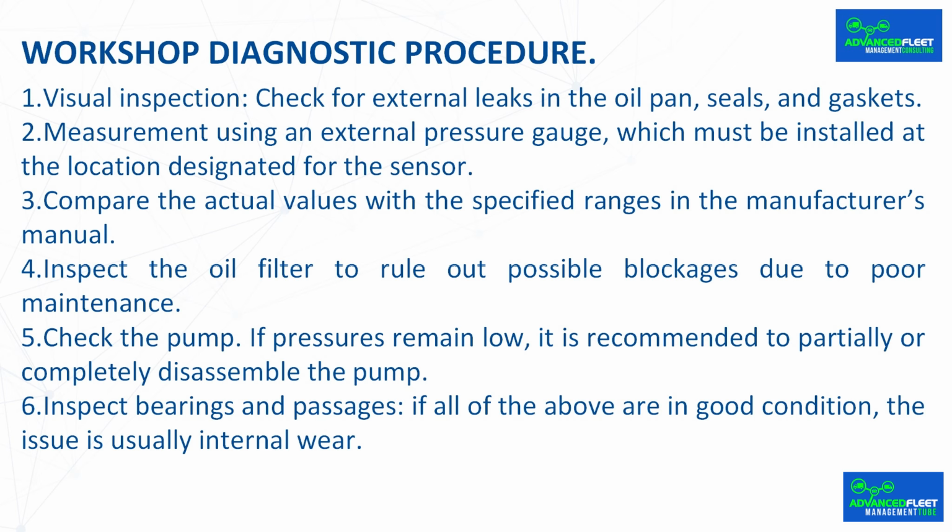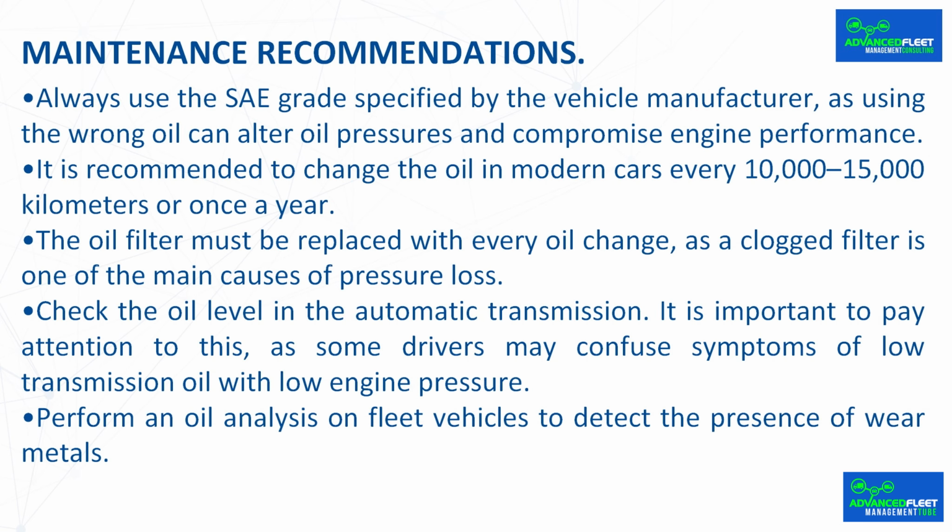Measurement using an external pressure gauge, which must be installed at the location designated for the sensor. Compare the actual values with the specified ranges in the manufacturer's manual. Inspect the oil filter to rule out possible blockages due to poor maintenance. Check the pump. If pressures remain low, it is recommended to partially or completely disassemble the pump. Inspect bearings and passages if all of the above are in good condition. The issue is usually internal wear. Maintenance recommendation.